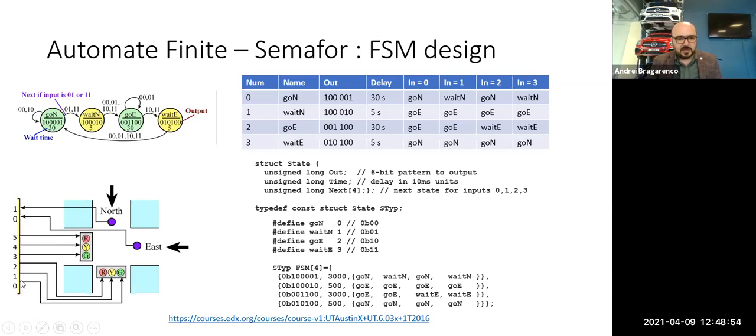And seeing this combination, for the go north, the LSB will be 1, and the MSB for the east will be in red. This is red and this is green. So now on detecting or staying here for 30 seconds, yeah, for 30 seconds. So on no one request, or we will have a request from 1 0 from the north, doesn't matter. We will stay here for the 30 seconds.